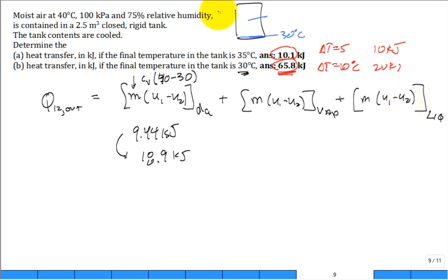If you understood this first part, great. Now we have to think about two parts for what happens with the water vapor. Some of it stays water vapor. Some of it, unfortunately or fortunately, whatever, condenses. And so what you have to do is say, what is the mass that stays water vapor, even at the end, and then what is the mass that ends up in the liquid state?